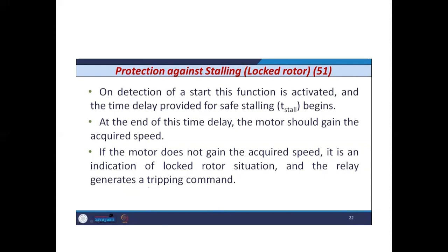But if the motor is not able to gain the specified speed before the stalling time expires, then this is an indication of the locked rotor condition.